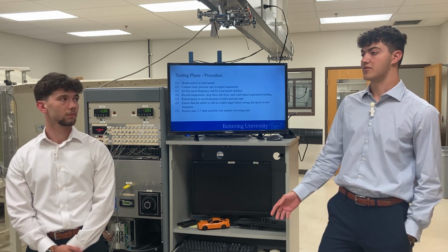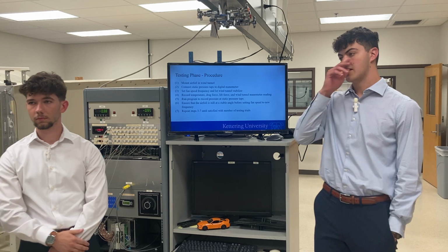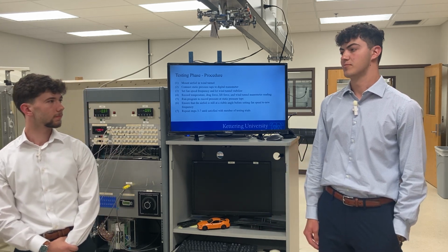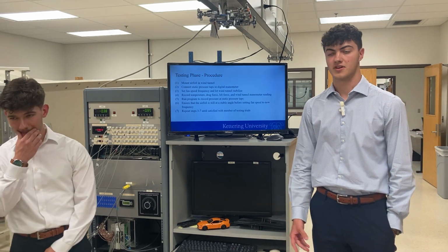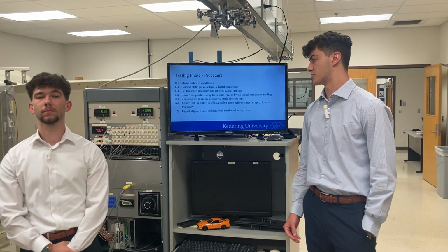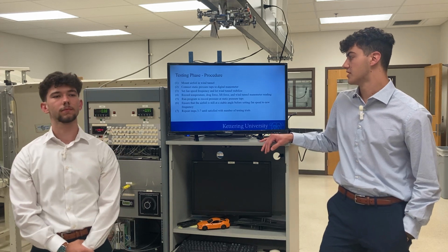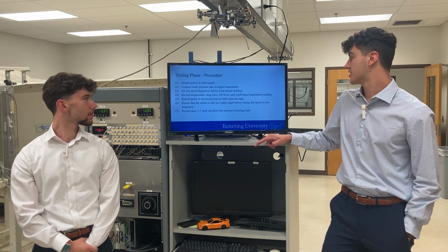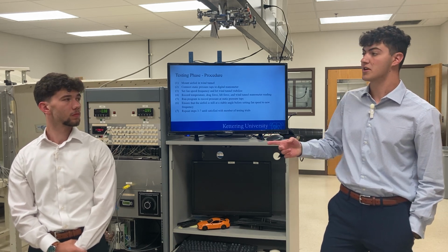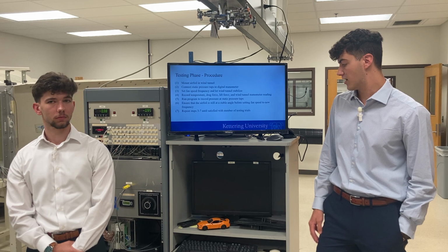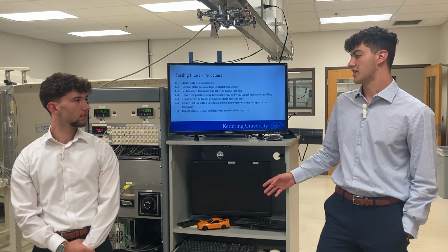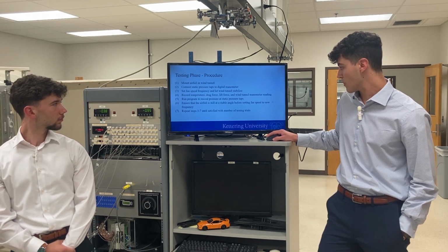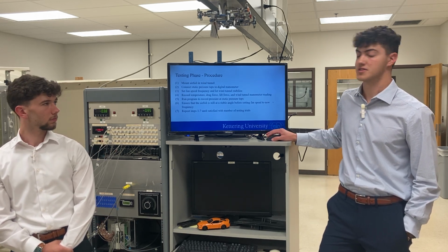once we got everything set up, we were able to turn on the wind tunnel, turn on and set the fan frequency, and basically let everything stabilize before we started collecting data to make sure that everything was running smoothly. So the components that we measured manually were temperature, drag, lift, and the wind tunnel manometer reading from the pitot tube. And then we also had the computer automatically calculate and measure the static pressure tap pressure points for us before moving on to a new frequency.